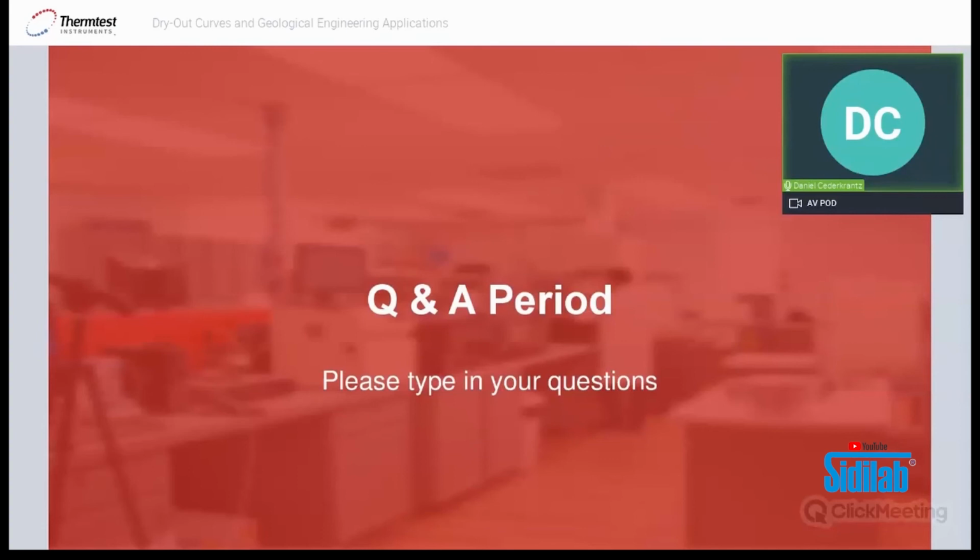You could also test. You could have a sample frozen, and you can pre-drill perhaps and test through the melting. That's doable. Just be a little bit careful if you test through the melt, because when you're in the phase change of the water in the soil melting, you do have a phase change, and during a phase change, heat is not really conducted.